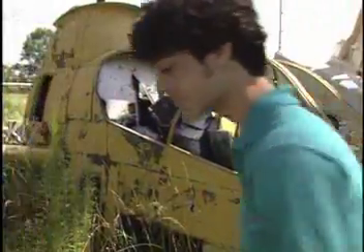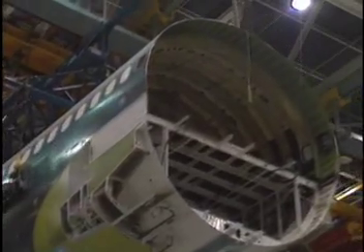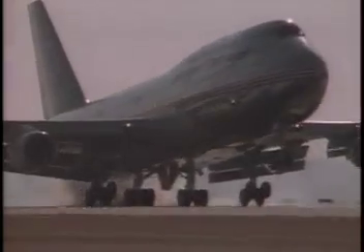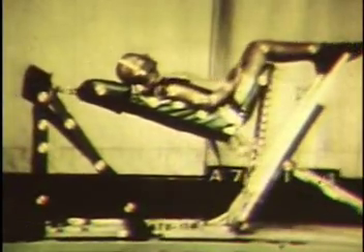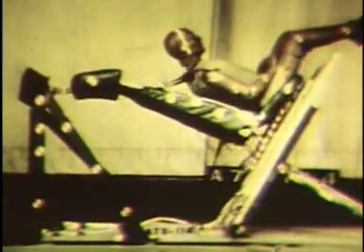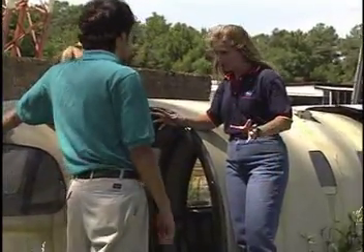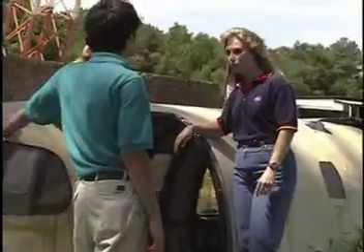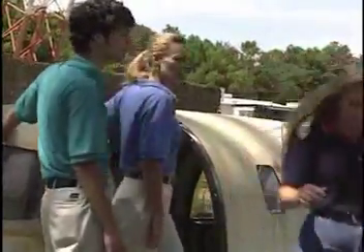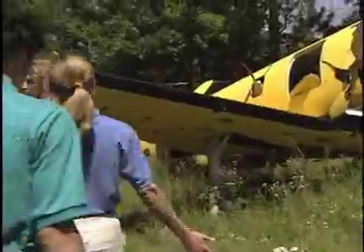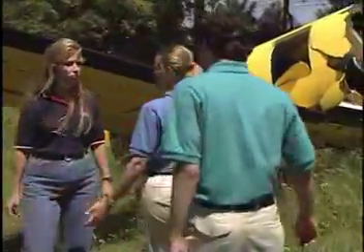Right. However, there are parts of an aircraft that can absorb energy in a crash. Parts like the subfloor, which is the area under the floor, the landing gear, the seat, and even the cushion can absorb energy. Restraints, like the seat belts, are also necessary to keep the passengers from flying through the aircraft during the crash. When these parts and structures are designed correctly, or optimized, the passengers have a better chance of surviving a crash. But Lisa, how do you design aircraft parts to absorb energy?